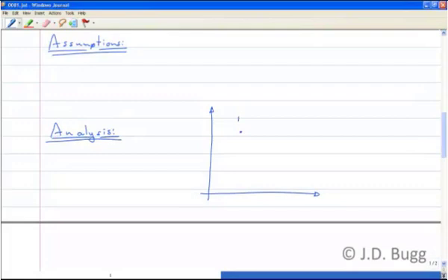So we're starting at point 1. And again, that point is fixed. We know that's at 1 megapascal, 650 Kelvin. First process is constant pressure. It says air receives heat from the surroundings at constant pressure. So that means this must be an expansion. Okay, so P, V coordinates, 1 over to 2 at constant pressure. Then an adiabatic expansion, and it's a polytropic process. PV to the K equals a constant, and it's an expansion, so it must go like that to 3.